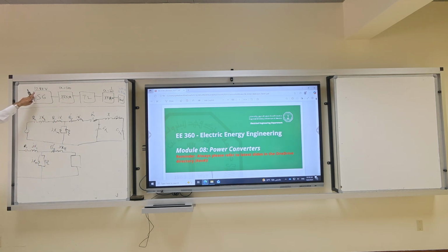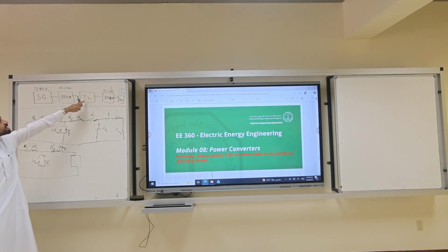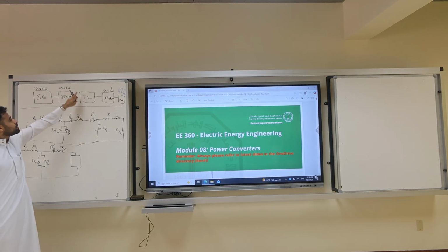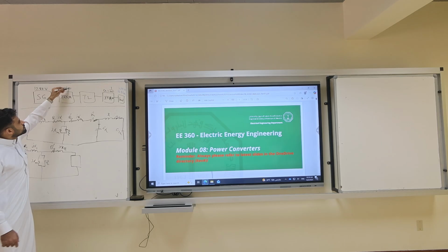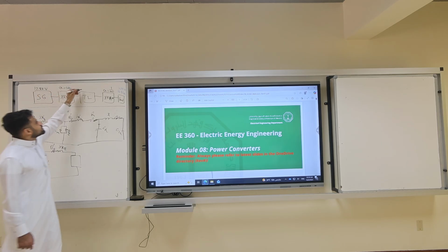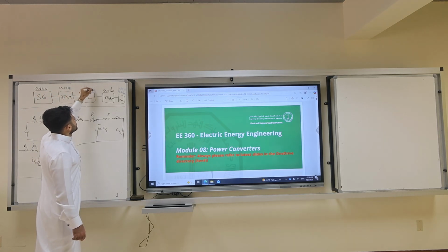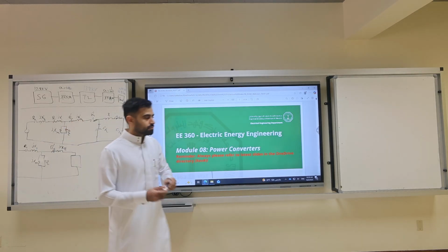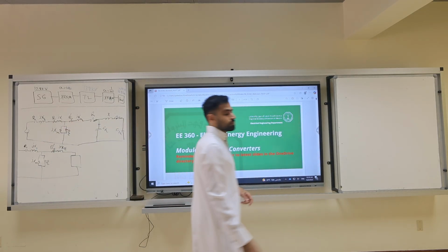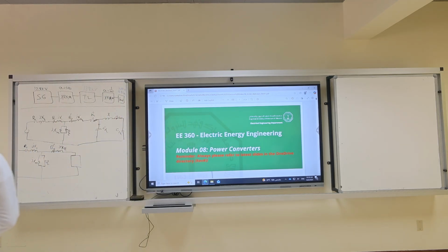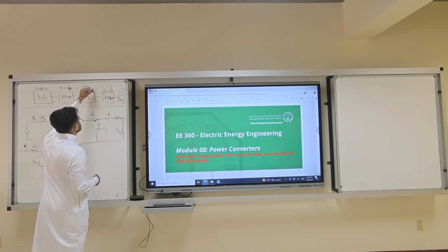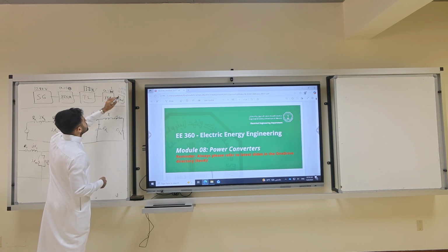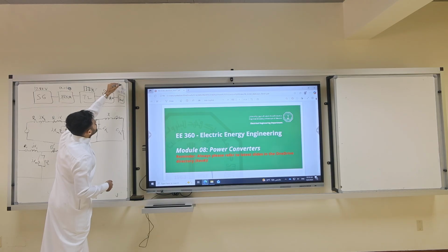He's telling you this is 13.8, so you know what's the transmission level voltage? 10 times 13.8, that's 138. Clear? So A is 10, this would be 138. This is 1 over 10, so what's the load voltage? 13.8.